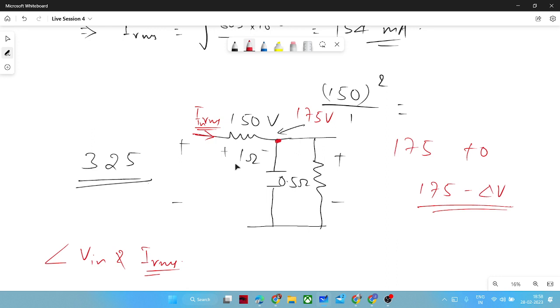But for protection, you need to compute from the circuit, right? In one question, it must be asked how much resistance we should connect in series with the supply to limit the inrush current. Since we will have some value of inrush current, from that we can compute the value of resistance that can be connected in series with the supply.